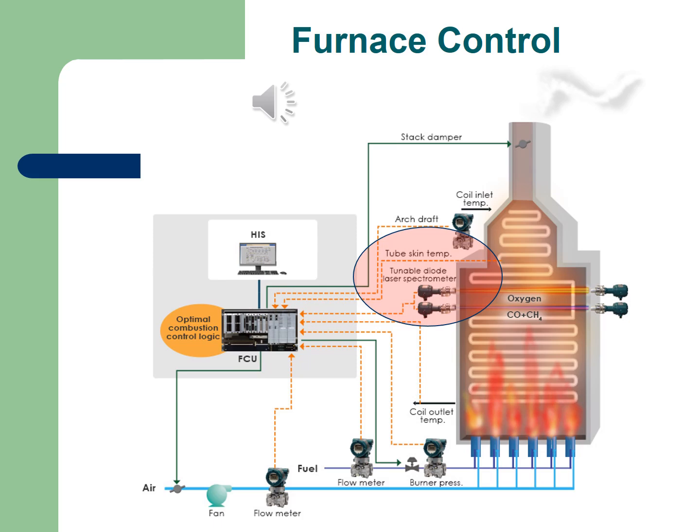That will determine if proper fuel combustion took place, if there's enough air and the right air to fuel ratio at the burners. So usually on furnaces you will use these types of analyzers to determine whether there was in actual fact a proper burning process or combustion inside the furnace.